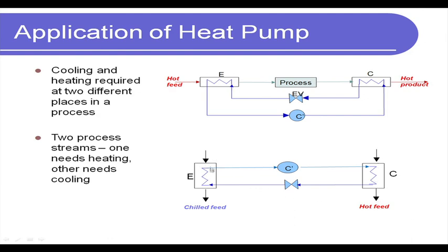Okay. So the first feed as it comes out is chilled, the second feed as it comes down is heated. Why? Because the refrigerant has rejected heat and condensed, thereby heating up this feed in the condenser. Over here the refrigerant at the low pressure has converted from liquid to vapor, and while doing so it has absorbed heat from this feed 1, if we call it so, and as a result the feed has lost heat and has become chilled or cold.